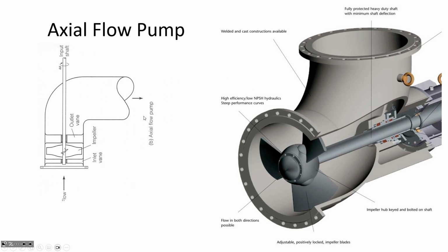So an axial flow pump is doing a similar thing. It's just increasing the pressure, and if you look at the velocity of the fluid before the impeller and after the impeller, the velocity of the fluid is the same. Because think about, you've got a constant diameter pipe that this impeller is situated inside of. And we know that flow in has to equal flow out. That's the continuity principle, that Q in equals Q out. As long as the diameter is the same, what that means is that the velocity in and the velocity out will be the same.